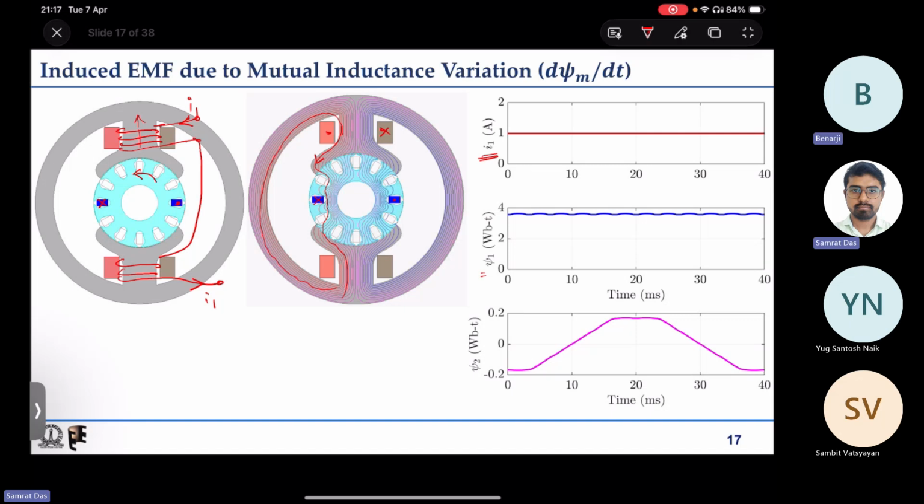For that only. So you are thinking that if the current flowing through that conductor is in this direction, then the flux will be upwards, and that direction is taken as positive. But in our case, the flux is moving from top to bottom, so we have taken it as negative at the zero instant of time. Correct. That is all. It is about the sign convention.